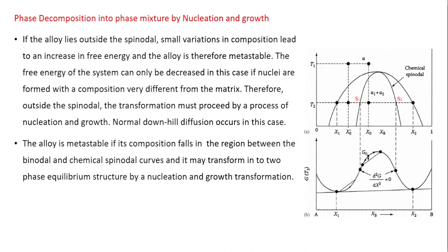Phase decomposition to a phase mixture by nucleation growth occurs if the alloy lies outside the spinodal. Say you have alpha of composition x0 prime cooled from temperature T1 to T2. Small variations in composition lead to an increase in the free energy, because this is the free energy of the as-quenched alpha,